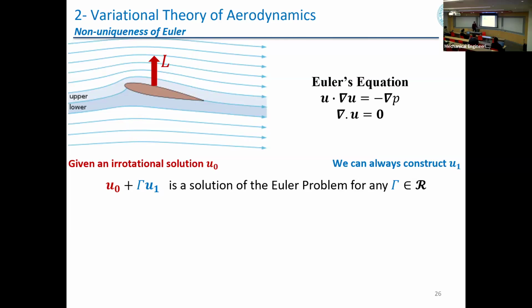So it seems that we have a one-parameter family of solutions, infinitely many solutions. And maybe this gamma is not important. What is the meaning of this gamma? This gamma is actually the circulation over the airfoil, which solely dictates the lift force. The lift is rho u gamma. Rho is the density of the air, u is the speed of the wing. So you give me gamma, I immediately give you back the lift force.